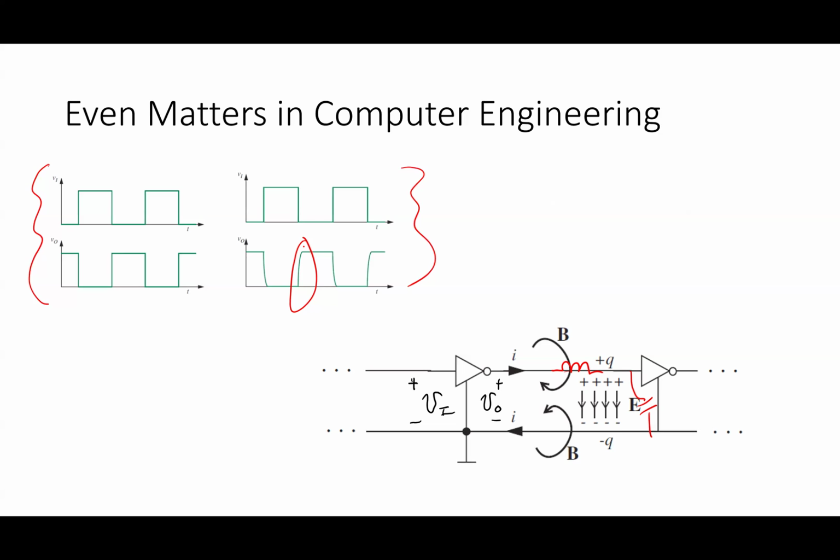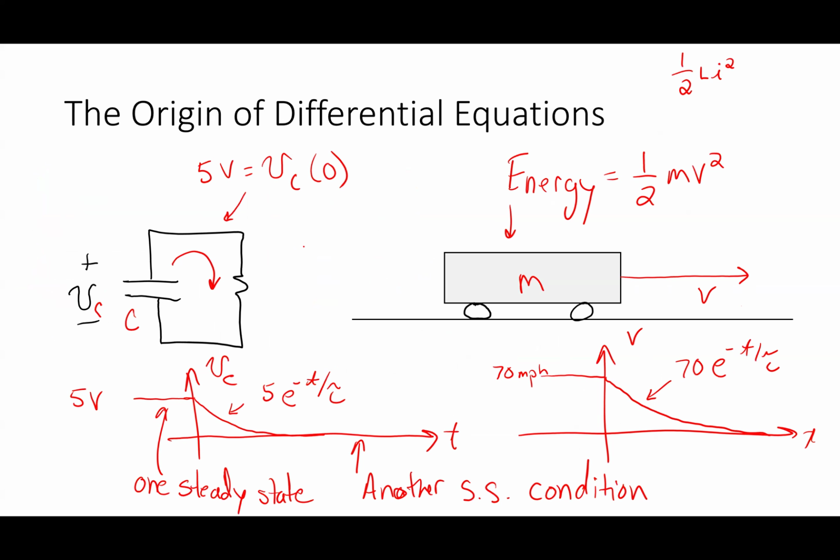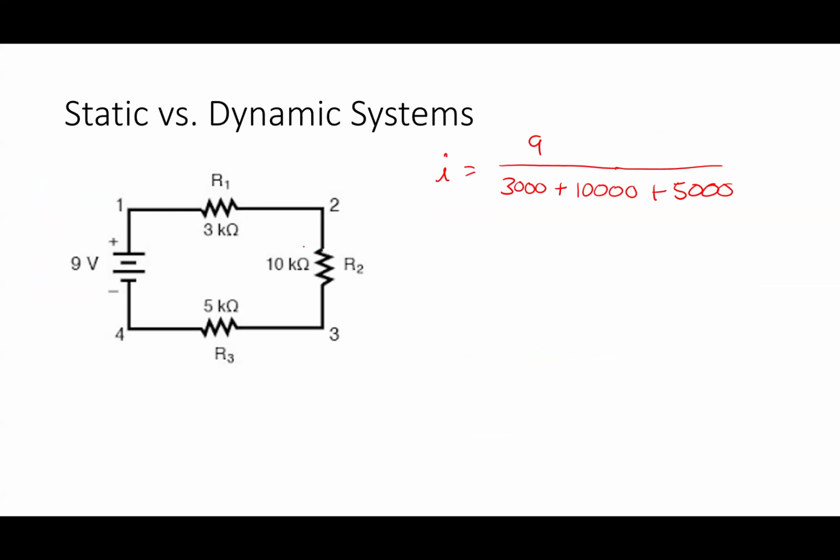All right. And that's one thing that we talk about a lot. I don't think you guys fully appreciate it, but like this circuit right here, yes, there's 3 resistors and 1 battery. If I built that in the lab, I would have 3 resistors and I'd have some wires. If you guys built it, your wires would probably go like this and then come back down. It'd be huge wires. Those wires have inductance. And so this is always just a model for whatever you actually build.